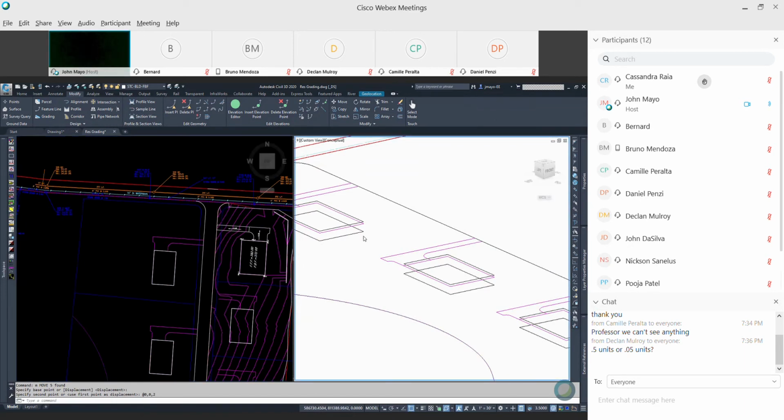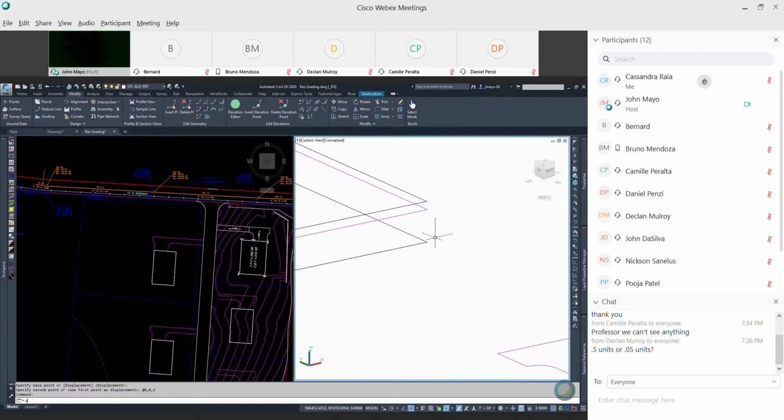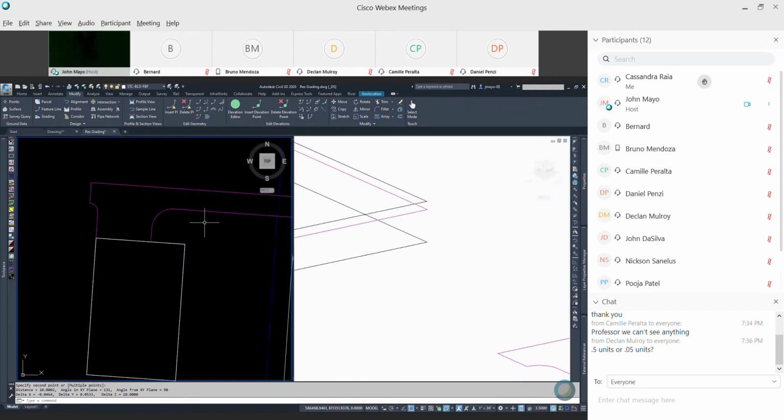I just made that relationship that I told you about, where if I use my distance command from this endpoint to this endpoint, you see we have our 10 foot from first floor to basement floor. It's getting that 0.2 because of the horizontal offset we have between the two elevations.